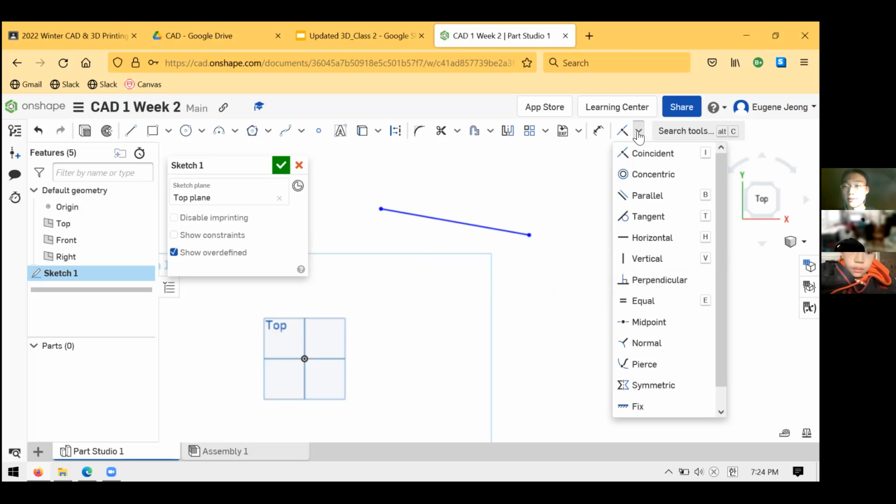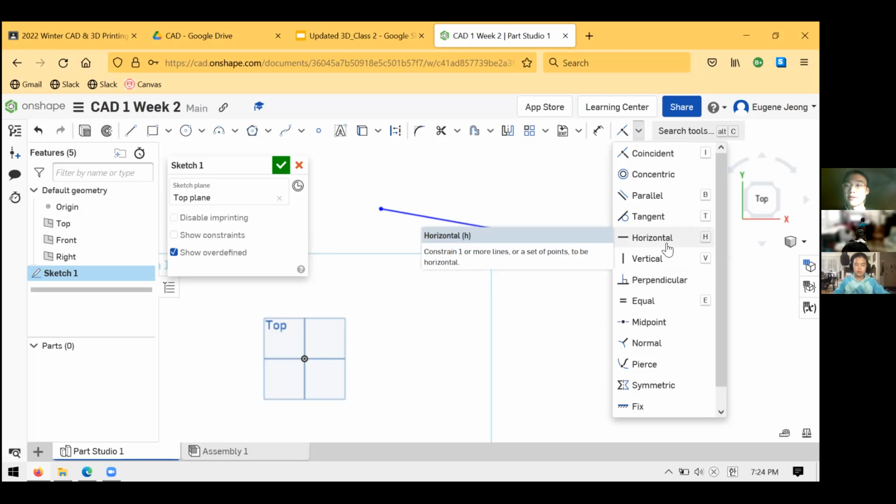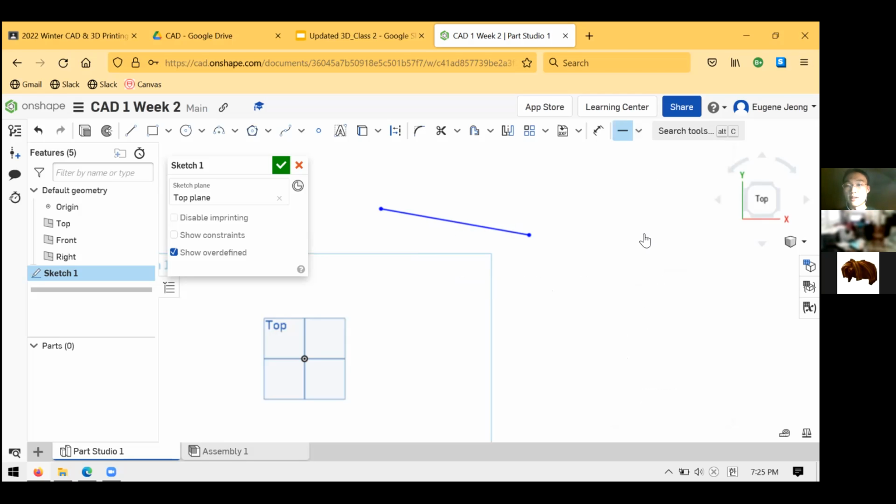And so the way you create a relation is using these tools, much like you'd use a line tool, for example. I'll start by showing you a simple relation, which is the horizontal one, just to show you how a relation works and how to use it. To start, just like any other tool, you click on it. You saw I dropped down, I clicked on horizontal, and it's highlighted, which tells me that I'm currently using a tool. Again, my mouse turns into a crosshair.